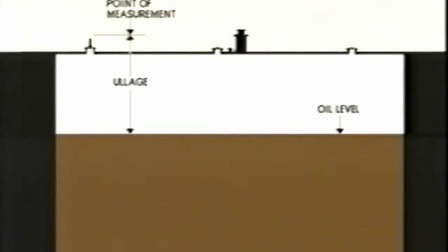Before discharge, the ullages are often checked manually. Here there are 2 measuring points in the aft ends of the tanks, port and starboard, each fitted with globe-type vapor control valves. Using a special electronic ullage tape, so-called MMC, you can measure the ullage without opening the tanks to the atmosphere.